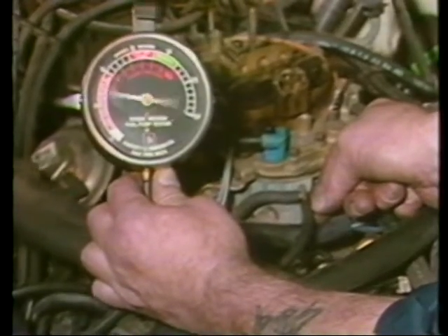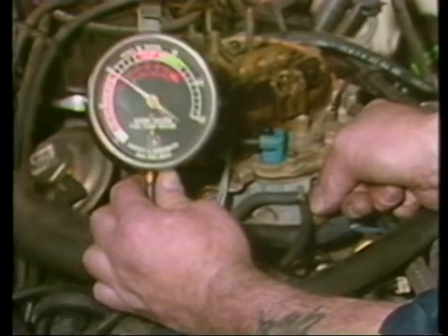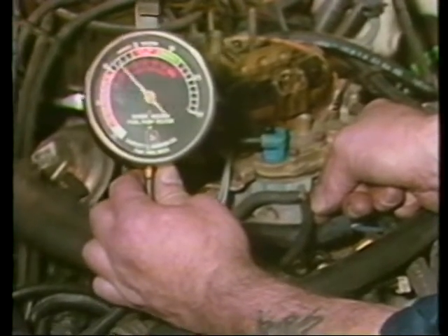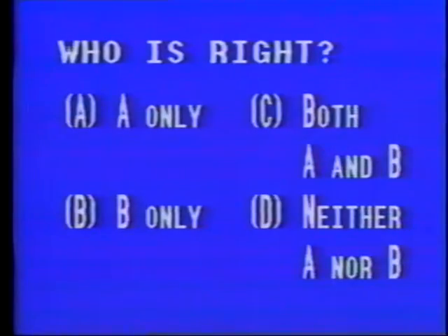If one or more of the cylinders had a leak in the cylinder seal, the vacuum gauge needle would drop on the intake stroke of those cylinders. The correct answer is response B for Technician B only. Vacuum readings at other RPMs and engine operating modes should also be understood as a diagnostic tool. Again, consult your reference material for more information.